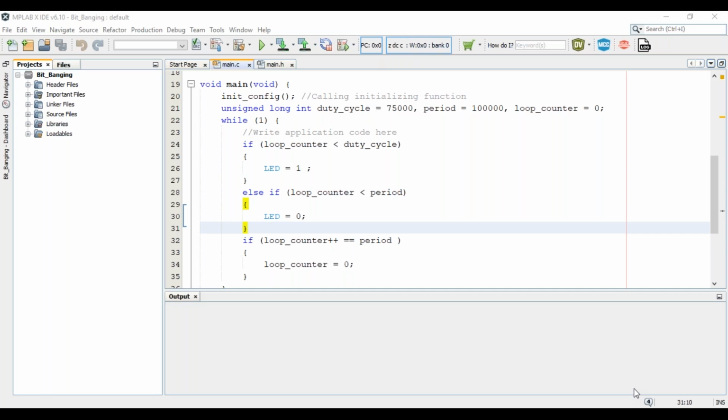Yes. The reason we do pulse width modulation is to control the average power being delivered to a particular load. So we change the duty cycle at a constant time period to deliver the required average power, right? Whenever we want to vary the average power delivered across the load, I have to vary the duty cycle, or vary the width of the pulse, keeping the period constant.